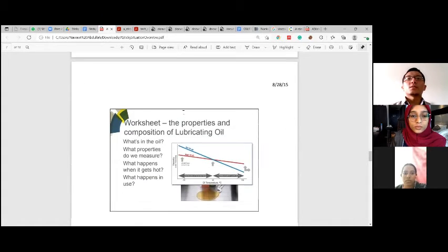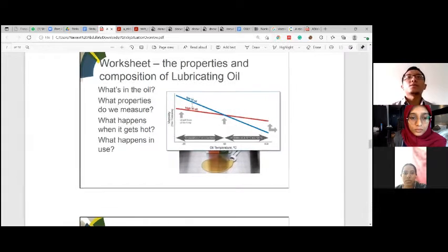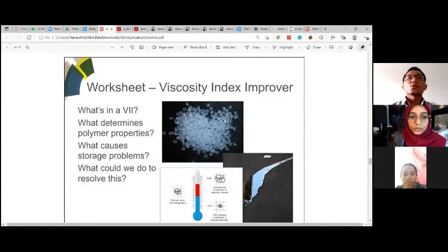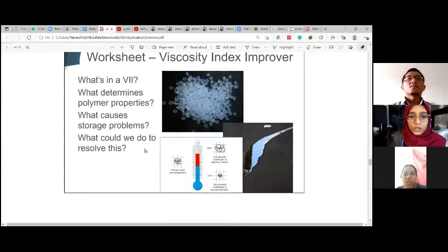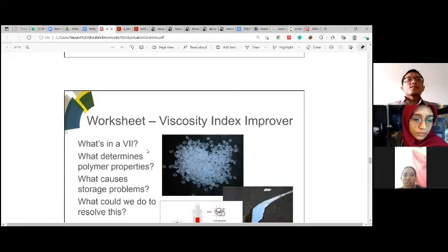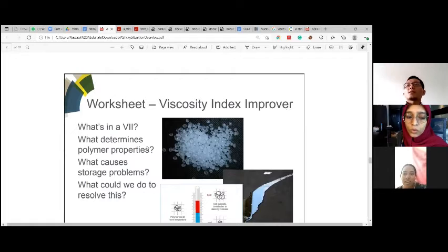answering the question. This part they were showing about the viscosity versus oil temperature. Yes, the thing that we need to focus on, I guess. Okay, correct. And then also the viscosity index improver influence. What do you mean by that? Viscosity index improver is also a thing that they add into the oil, right? Yes, to get a nicer viscosity of the oil, to control the viscosity of the oil against temperature changes.